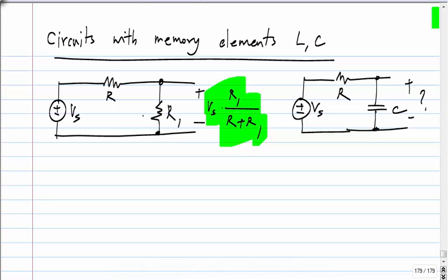So, you imagine that this is some voltage, let's say Vx. First, you write KCL: Vx by R1 equals the current flowing from there, Vs minus Vx by R. Okay, and you solve for this. So, what should you do in this case?